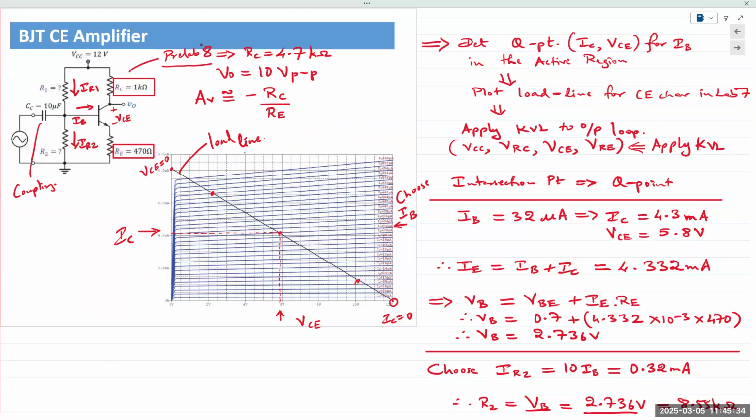Okay. So if you analyze this using the load line technique, we do exactly the same thing. We'd want to determine the load lines for the input and the output side. Actually, in this case, we just want the output side. And then we want the input points, meaning where it's swinging. That means I want the current input that's going into the base, my AC input current, right?